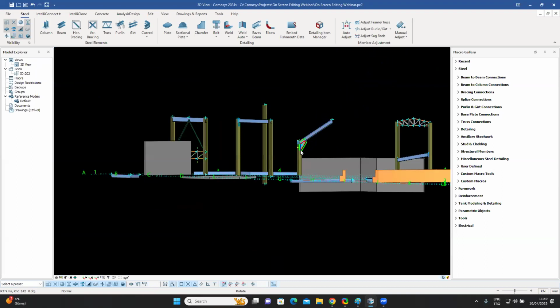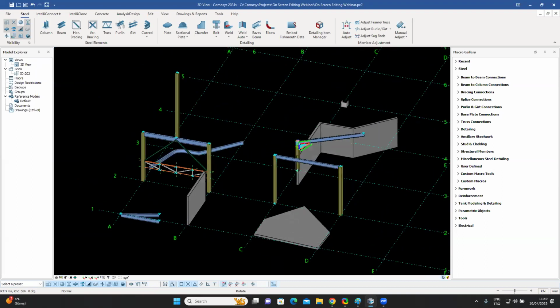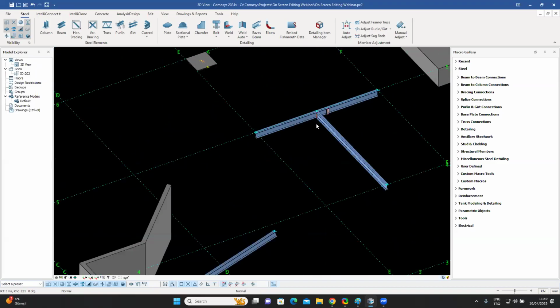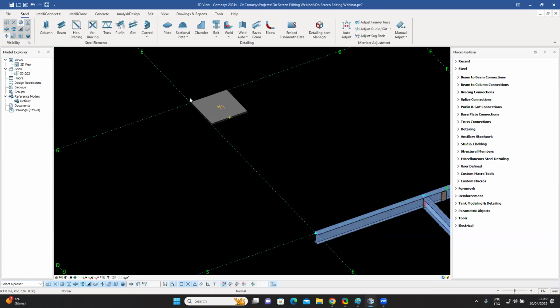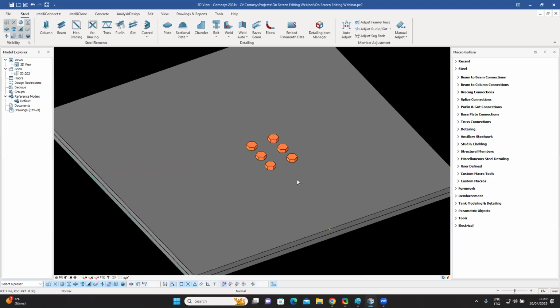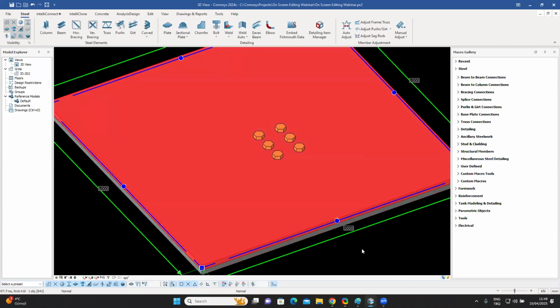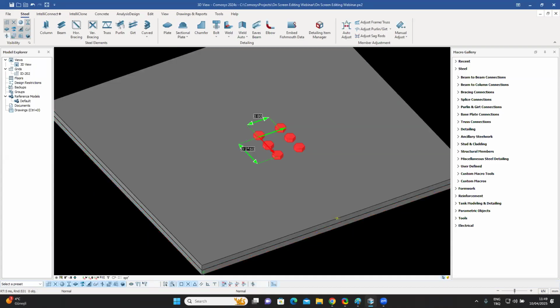Let's move on to some bolts, for example, over here. I want to talk a little about bolts. One feature which we have right now is that the bolts also have their handles. So if I select a bolt, there are two plates over here, and they've been bolted together. If I select a bolt, one thing I see is the control Q, which was used for rotating profiles, is available over here to reverse the direction of the bolts. So I can use my control Q to reverse the direction.